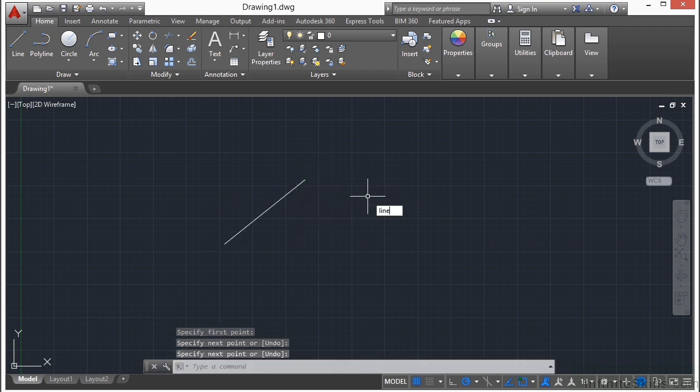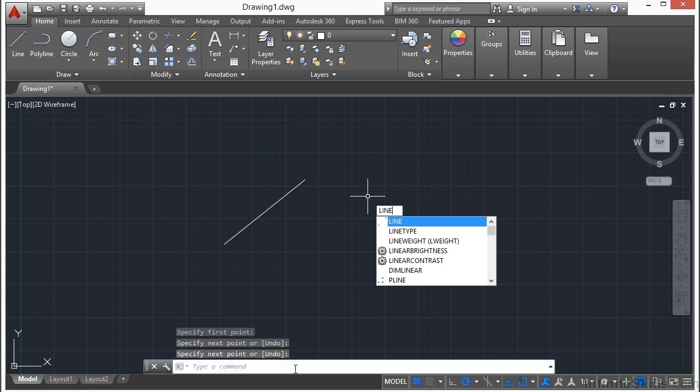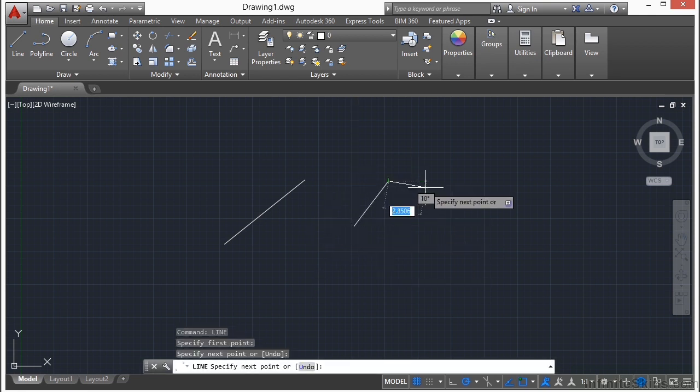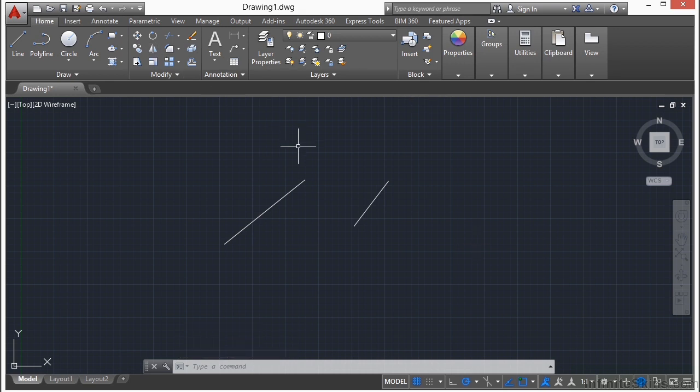Also, I can just start typing. I don't necessarily have to put it down in here. And what's going to happen is one of two things. Right now I have on what's called dynamic input. And that means I'm inputting dynamically while I'm working right at my cursor. Now this sort of emulates a smaller, more condensed version of the command line. And you see I can start drawing lines right away. We're going to talk more about the ribbon, the command line, the dynamic input, and all these other items that you're going to use.